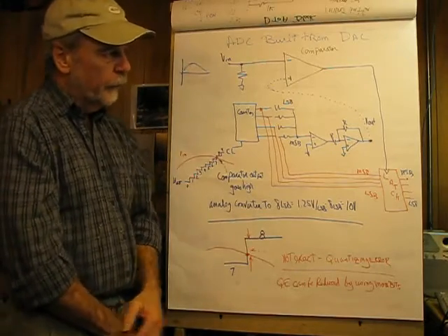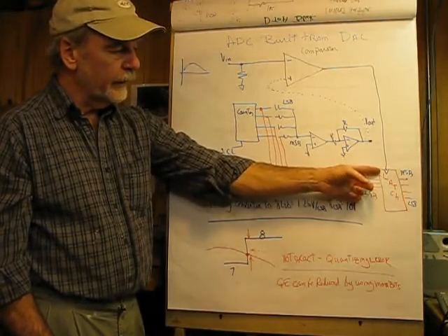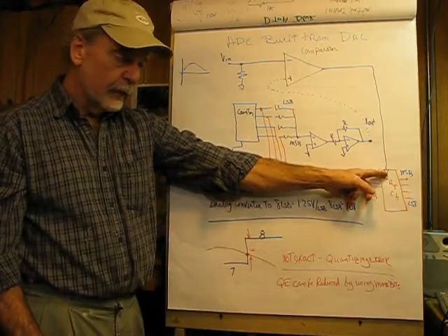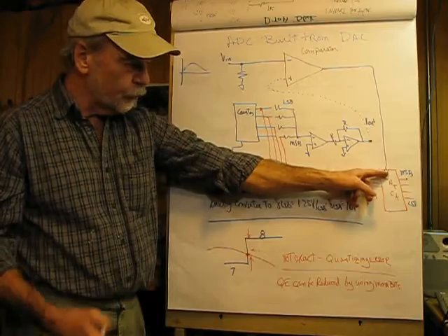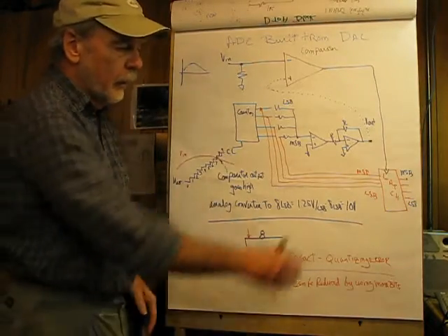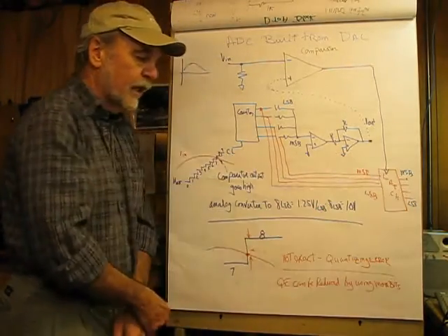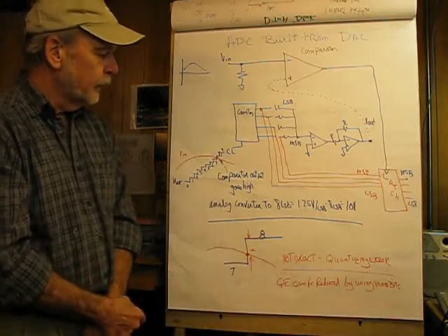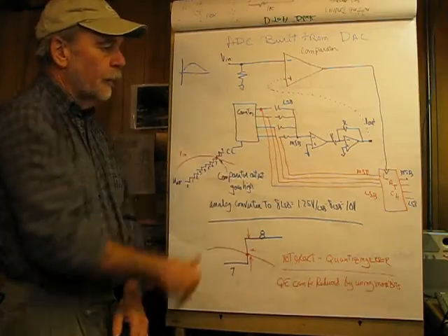And then what we're going to do is couple the output of this into a latch, and this will take a snapshot of the inputs when the output goes high. So this is a dynamic positive edge triggered input, which will cause the latch to latch. Then when it does latch, what appears at this side will be latched on the other side for further processing or whatever.